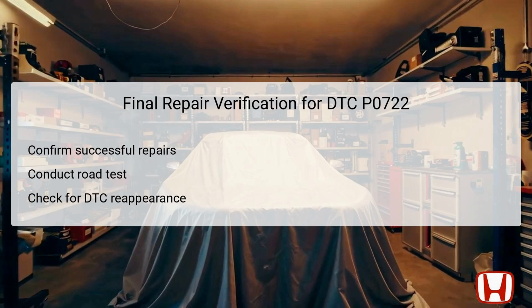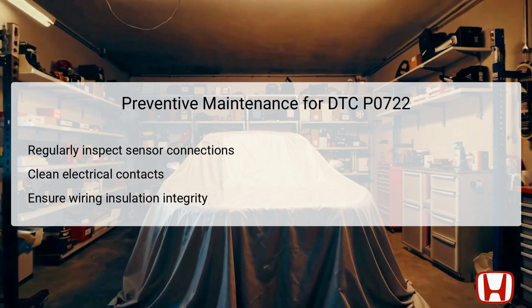During this test, pay attention to the vehicle's shifting and acceleration to ensure that they are functioning smoothly without any discrepancies. Post-road test, recheck the onboard diagnostic system for the reappearance of the DTC, ensuring it remains cleared after repairs. This final step validates that the troubleshooting and repair processes were successful, confirming the vehicle's wiring and sensor are functioning optimally. Preventive maintenance plays a vital role in avoiding issues like the DTC P0722 in the future.